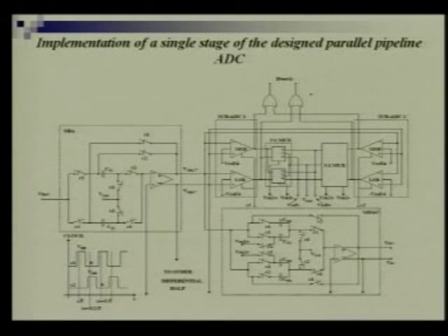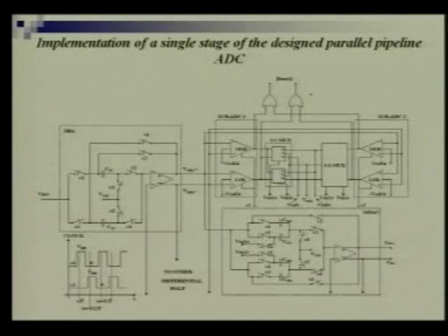One technique I would also like to mention: when you are really fabricating some chip, don't go for the final block in the beginning. You will have to make all these building blocks and first check whether they are functioning well or not. So it should be in 2 steps. The first step, you just design the building blocks, see how they are performing, and then you combine them and see how those things are doing. That will be a much better approach than going ahead with the full design. You may find that the things are not really working well.